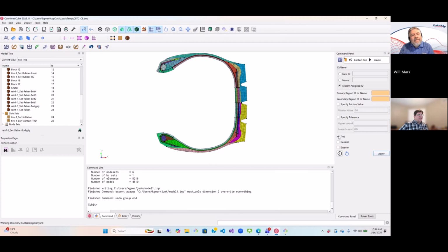For this particular case, the way that I implemented rebar, and once again, this is just the way I implemented rebar, I implemented it as the plies being two elements thick so that I could find that midline easily. Yeah, could we go back and remesh this as a coarser mesh? Yes, getting high quality mesh as you go coarser becomes more difficult. But if you're doing a footprint mesh, you may not care about quality quite as much.